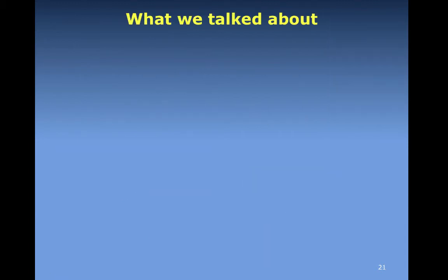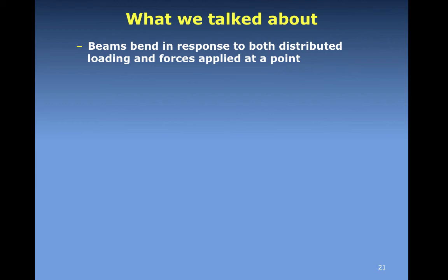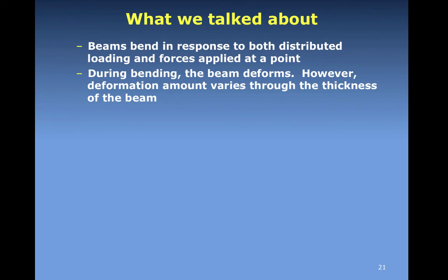Now that we outlined the theory and provided you with the governing equations for stresses in the beam, it's worth pointing out a couple of highlights from this lecture. First, remember that beams bend in response to loading that can be either distributed or acting at a point on the beam, and that clearly in response to this force, the beam will deform. Remember though that the amount of deformation will vary through the thickness of the beam. For example, there could be compressive deformation on the top of the beam and extensional or tension on the bottom of the beam.